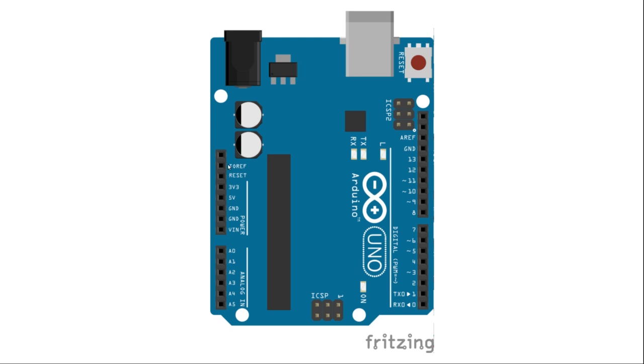The next pin is the reset pin. It will reset the board and start the execution from the beginning. It's equivalent to pushing the button on the top right corner of the screen. The next two pins are the voltage output. They output 3.3 volts and 5 volts respectively.